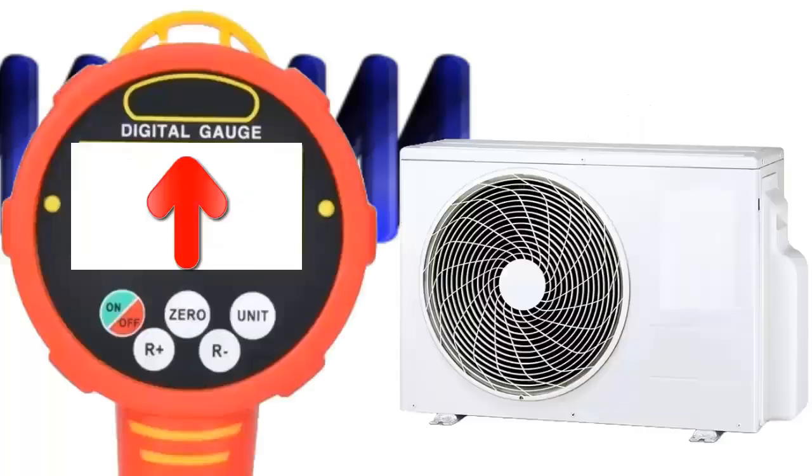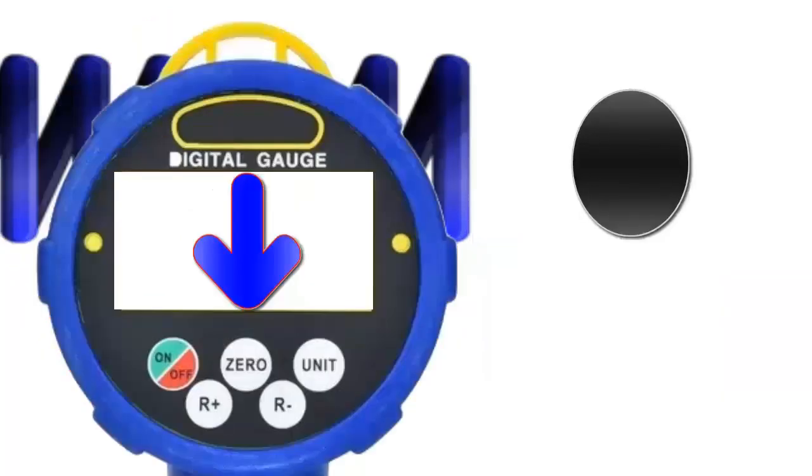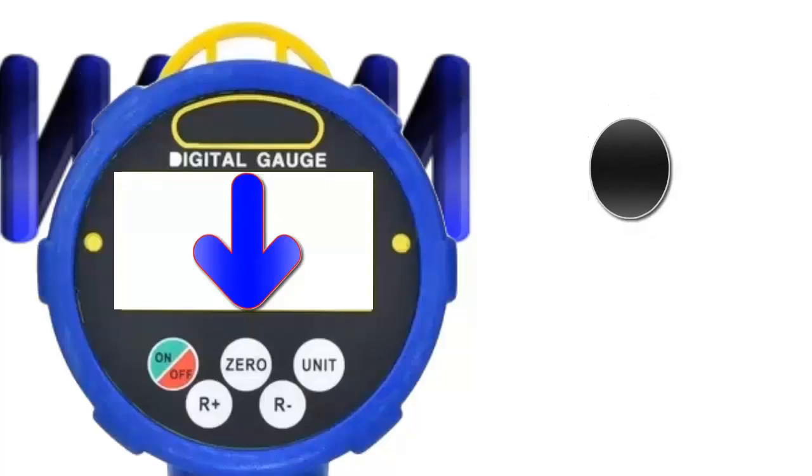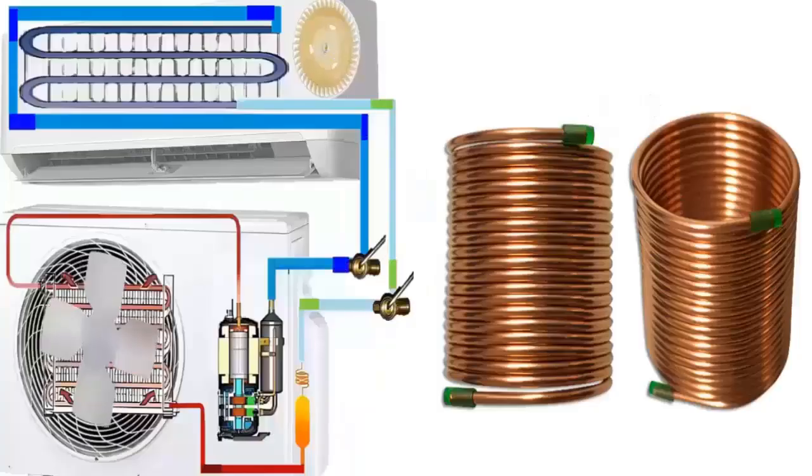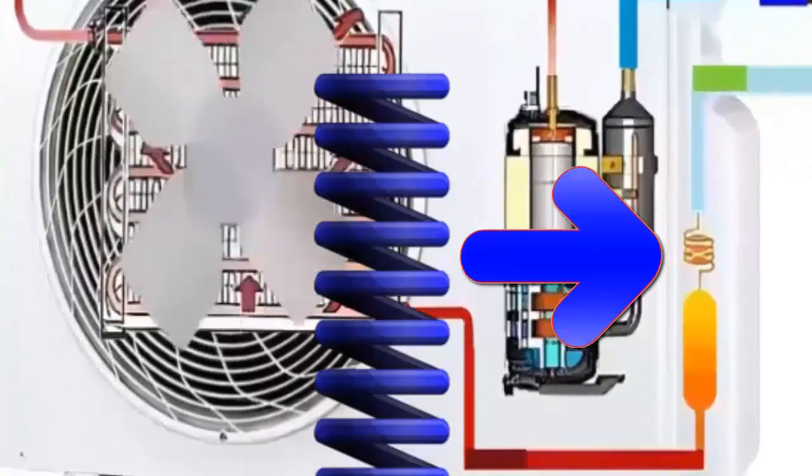Case 4. Capillary tube with a smaller diameter than required. If the capillary tube has a smaller diameter than needed, the main effect will also be observed in low pressure. In this case, low pressure will drop significantly due to the higher restriction imposed by the narrower tube. As a side effect, high pressure will increase, leading to higher electrical consumption by the compressor. This increased energy consumption could reduce system efficiency and cause overloading of the compressor motor.